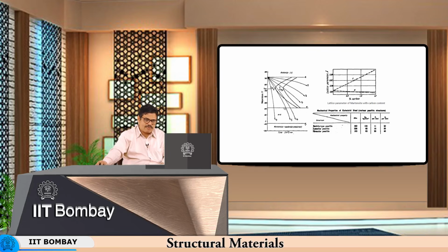So, here you will have the entire austenite getting transformed to martensite, and here you have clearly missed this nose of the temperature time transformation diagram, and therefore, the cooling rate is too fast for anything other than martensite from getting formed. So, the entire austenite therefore gets transformed to martensite.